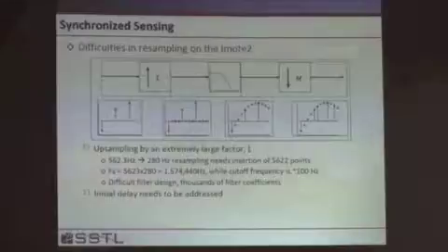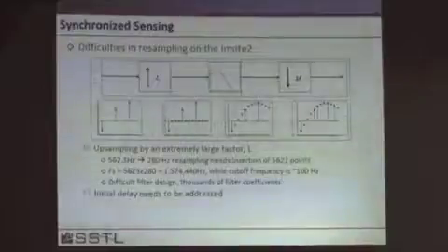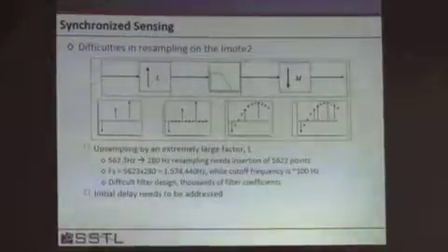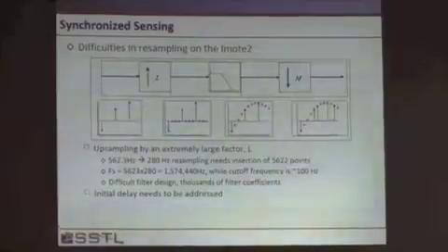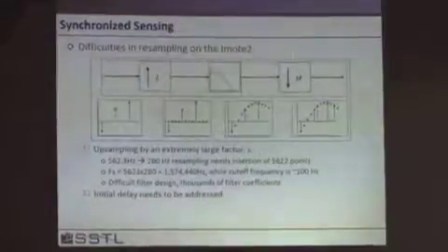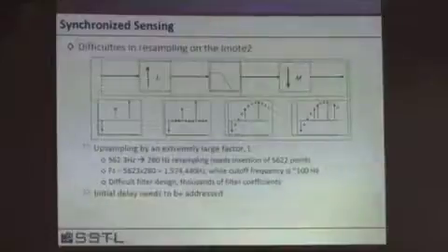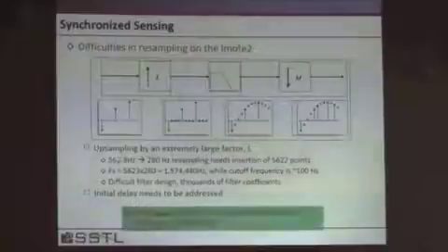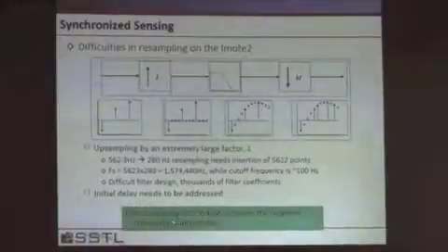So if there's just a few microseconds between the sensors, you might have to resample at 1,000,000 hertz. If you have to resample at 1,000,000 hertz, what do you do with all that data? So the approach that's taken is that we upsample the data, we filter it, and then we downsample. But as I said, direct implementation that achieves the required resolution is intractable.